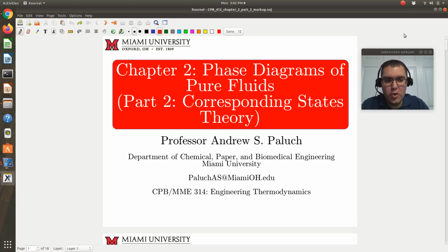So this is part two of our notes from chapter two. Here we'll begin to talk about the quantitative modeling of the PVT phase behavior of our fluids. In the first set of notes, we just looked at PVT phase diagrams, mainly pressure versus volume, pressure versus temperature, and then pressure versus compressibility.